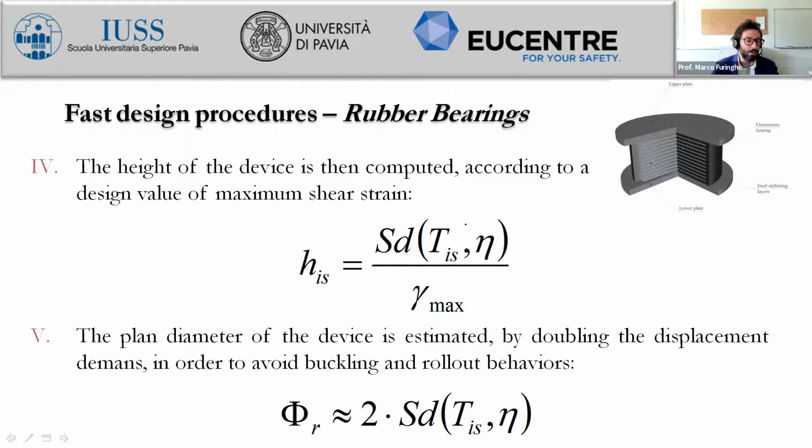If you consider a higher shear strain, you want to displace the device much more than the length of its height, and so you will get a smaller height with respect to the lateral displacement, according to this expression. And I just want to highlight that according to this definition of the shear strain, the deformation has to be considered like this.